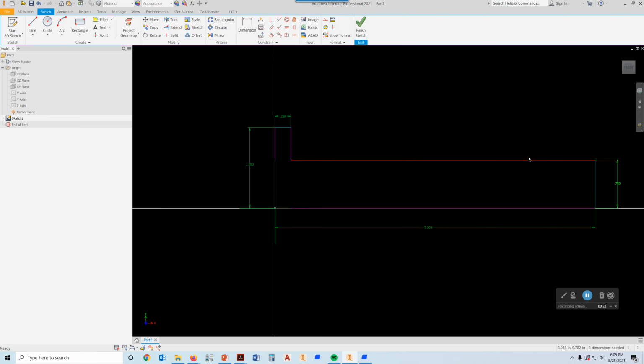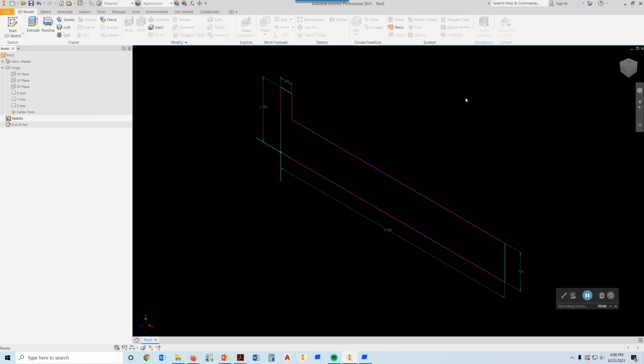All I've used are the same dimensions that are on the sketch of the tool slide 1433. And as I said, you don't have to trim these out, but you have to watch out when you do the extrusion that you select this rectangle and this rectangle to do the extrusion. So I'm going to choose Finish Sketch because I'm finished with the sketch at this point.